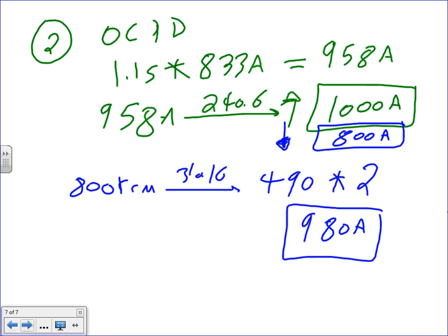Any question, guys? When you do your calculation, the only thing you need to check is, can the conductors handle the overcurrent protection device, because you're protecting conductors? Is the overcurrent protection device higher than the conductors? Yes. Had this situation been 800 amp or less, no problem. Had this been 700 amp and this 650, no problem. Stay where you are. But because we exceeded the 800, you have to match the overcurrent protection device to the conductor, or the conductor has to be higher in amps.